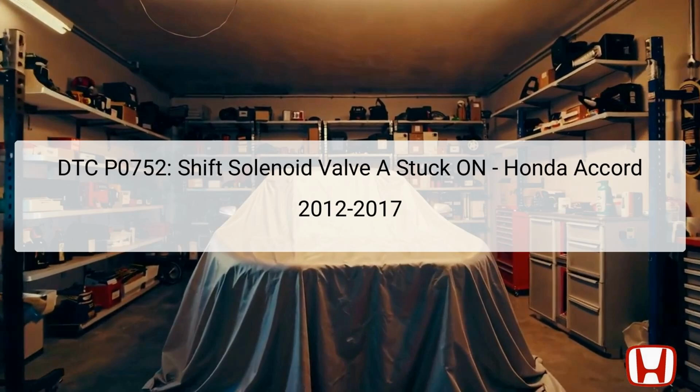DTC P0752 indicates an issue with the shift solenoid valve A in the Honda Accord models from 2012 to 2017. This particular code suggests that the valve is stuck in the on position, which affects the hydraulic pressure supply to the clutch. The shift solenoid valve A is crucial for managing gear shifts by controlling the application of line pressure to the transmission. It is typically found mounted on the transmission housing, making it relatively accessible for diagnostics and repairs.